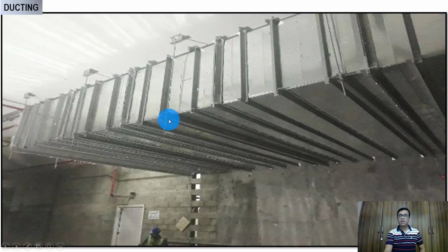Look at the ducts over here. I can just explain to you. This is a joint, and this is not a tedious joint. This is the joint reinforcement. Even if there are grooves over here, we have added joint reinforcement. You can see the intermediate reinforcement. You can see the kind of material being used and how ducts are properly installed. See these reinforcement joints. You can see proper bolting and proper gasketing.